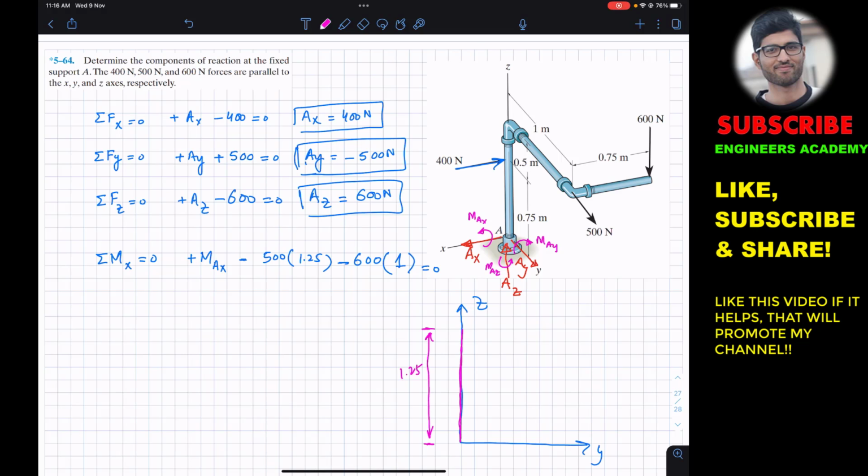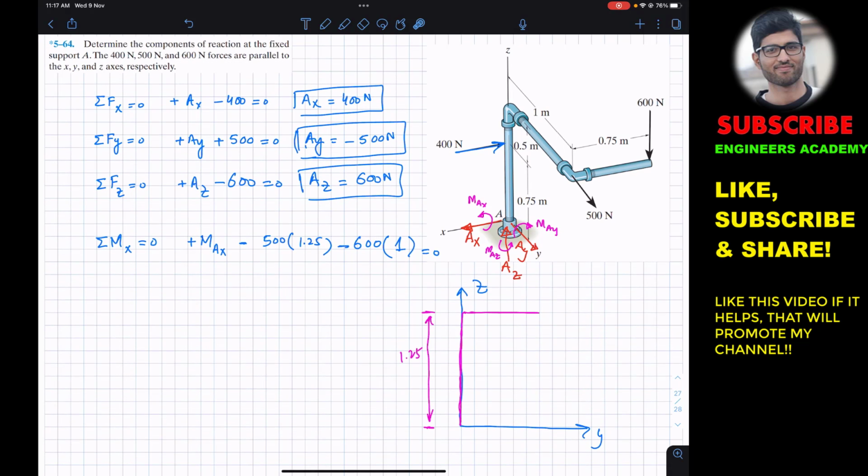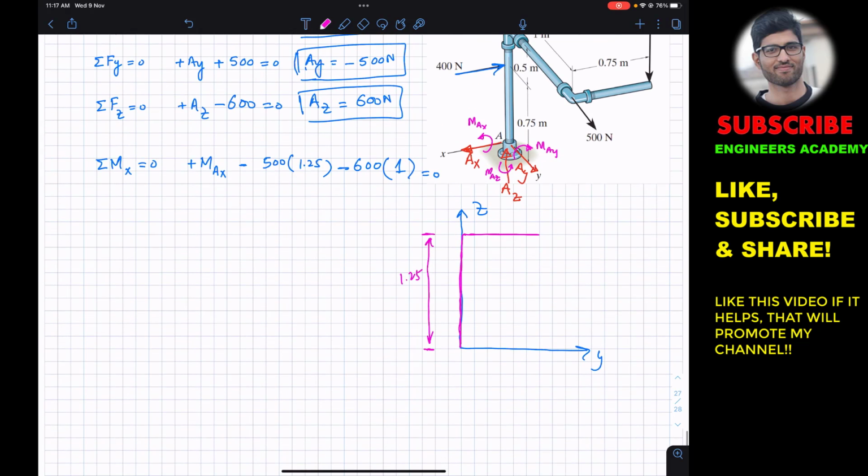Then the pipe is bent towards the y-axis, and it is 1 meter. Then the pipe bends towards the x-axis. So if we look into this mechanism from this side, from this point the pipe goes into the screen, so we cannot show this part of the pipe in our 2D diagram. This is the free body diagram in the YZ plane.